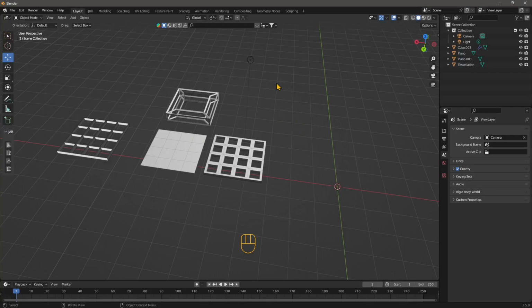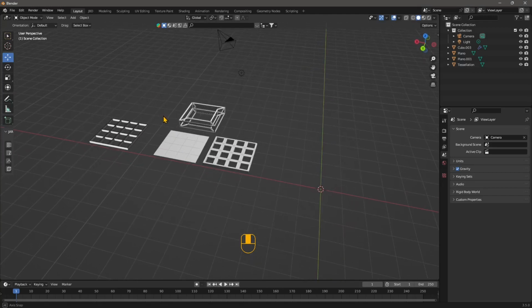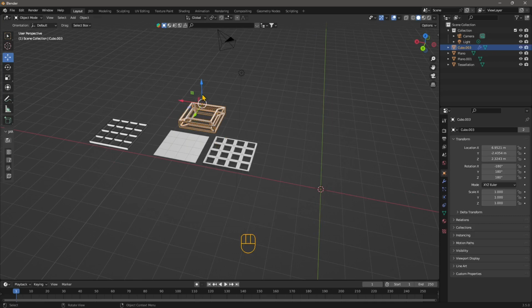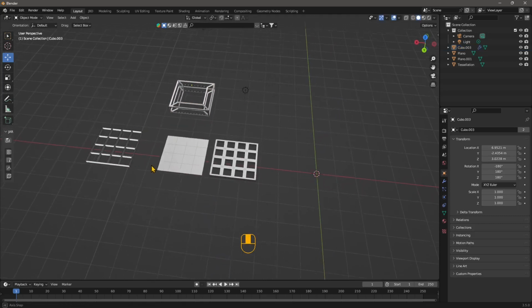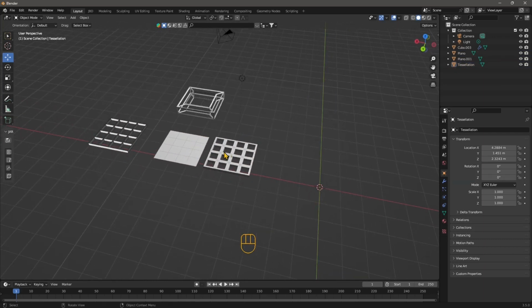In this video, we're gonna talk about Lattice in Blender and how we can use the Lattice modifier to create complex shapes, and also how we can create a wireframe that can be visible in 3D, so 3D framing essentially. And with this, create like the mullions for a curtain wall, or the frame for a picture or for a window, and so on. So similar objects.